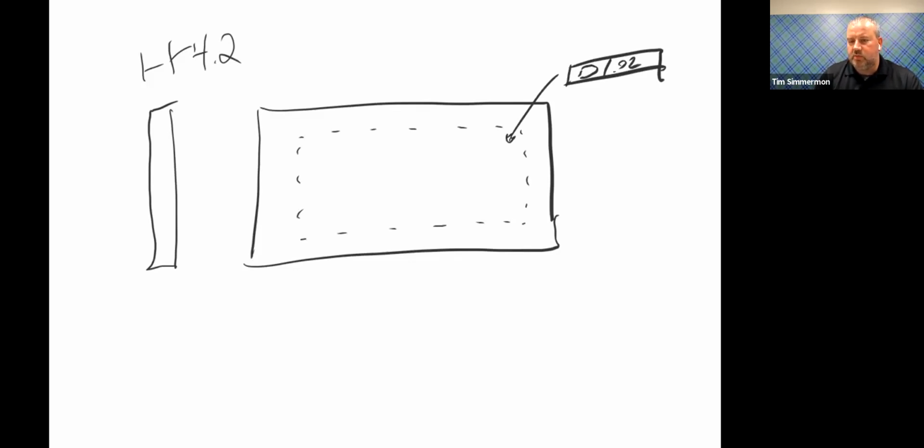So you start to see that in the industries that Scott Forge works in, where the parts are absolutely gigantic. 100,000 pound components that are going to fit into other assemblies, but not the entire face of the part is going to be touching something else in the assembly. So to try and hold that tolerance across the entire face is not cost effective. So what they'll do is they'll add in dimensions on the part and say, only for this 2-inch by 1-inch box that's located a 1/2 inch in from the corner, you have to hold that flatness, because that's going to be the only area that makes contact with something else during the assembly.